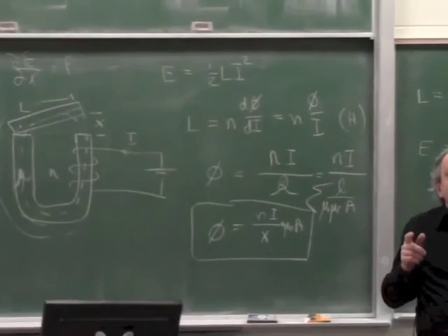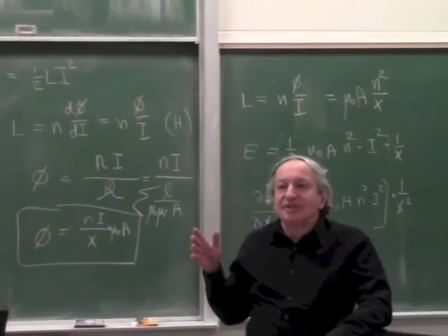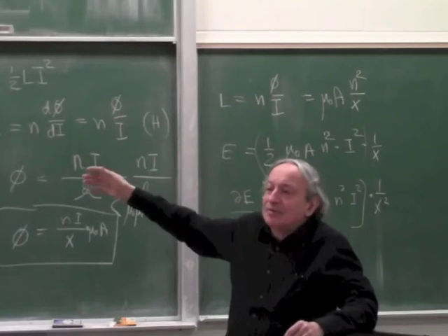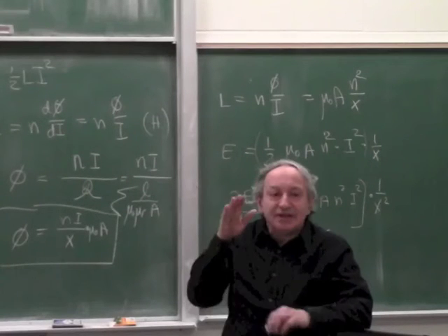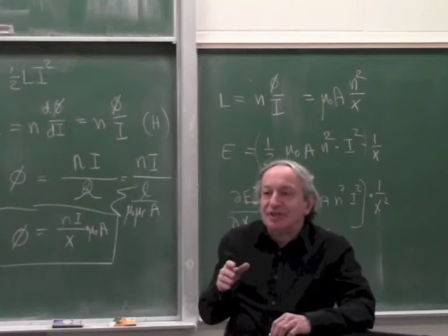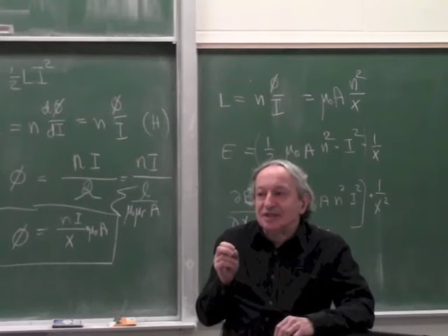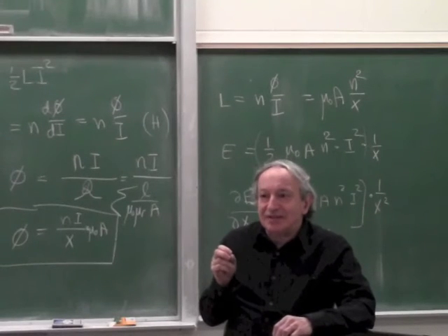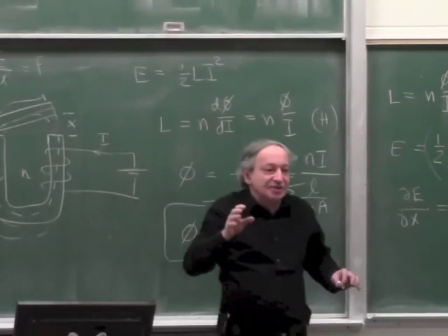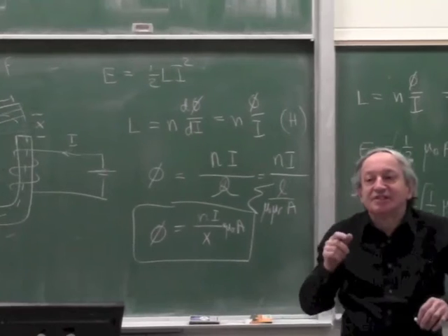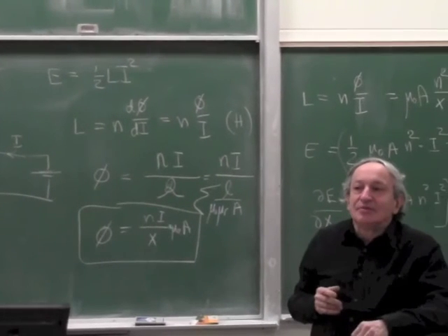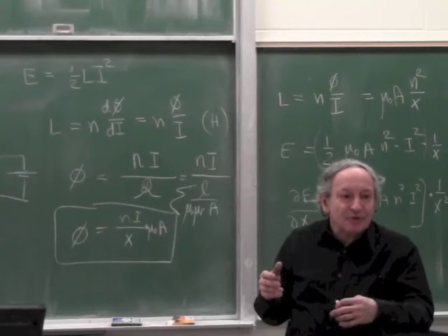Now, if the gain becomes very high, and all the other properties are the same, because the inductance, the phase shift, inductance not, but the other mechanical properties are the same. If the gain becomes very high near closure, you have to design the filters and everything for stability. So you have to design the system so that it's stable at the highest gain. Where this armature is almost closed, you have to be very careful with the phase shift and everything, so that it will still be stable at the highest gain. Which means, at a different gain, the system will be sluggish, underperforming.